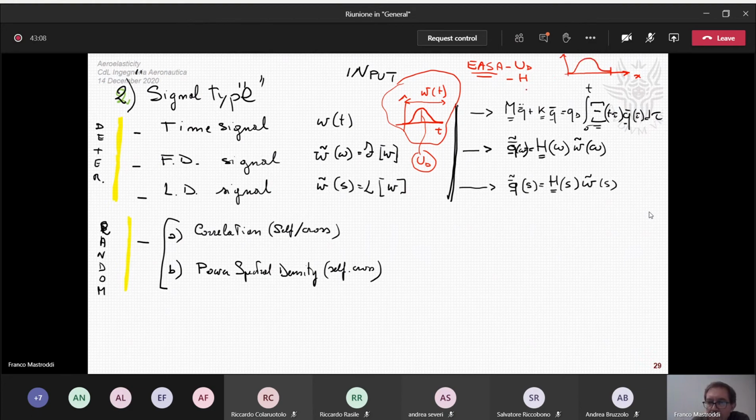And so you have a formula like 1 minus cosine of 2 pi x by H. So you have different lengths of your bump. This is the aircraft coming. So check your aircraft response considering several UD, several H. It is your V as a function of x. So this is the deterministic scenario for designing your aircraft by considering a possible deterministic gust input profile.